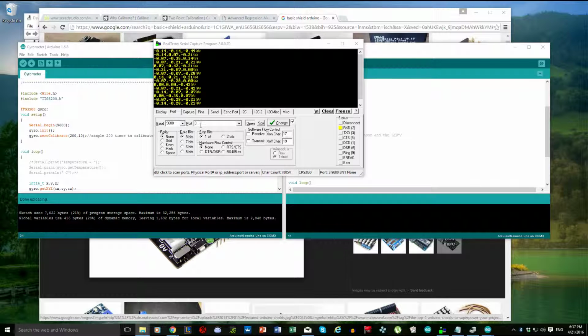So yeah, port 3, BAUD 9600. It is open right now, and you don't have to change anything here. Right now it's showing you the command line, or actually I think it is Windows something. It doesn't matter. It is showing you the numbers taken from the sensor. These letters at the end, you don't pay attention to them. It's showing you that it's taking the data from the sensor and not from somewhere else. Then now you have to go to capture.